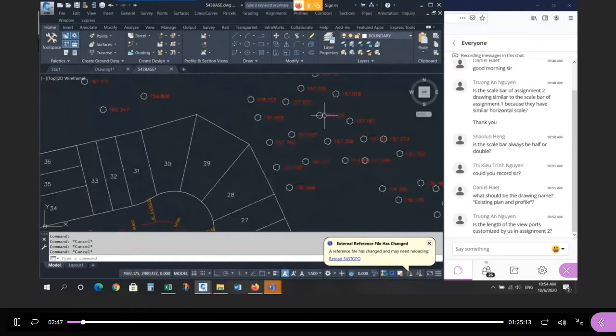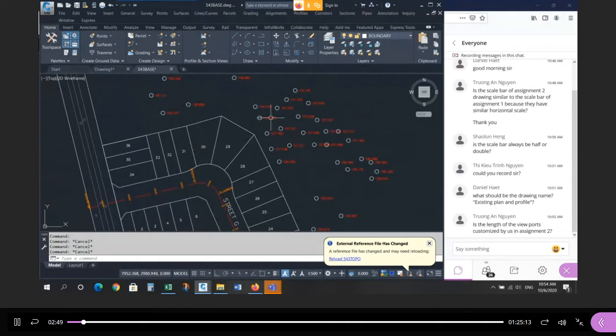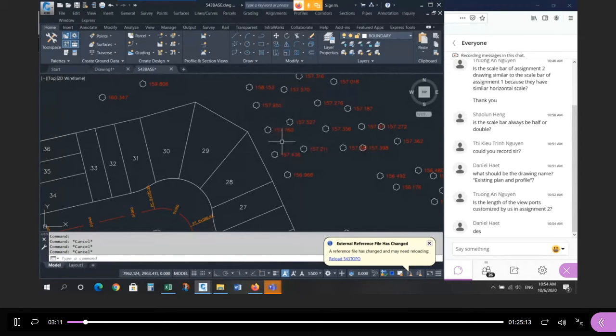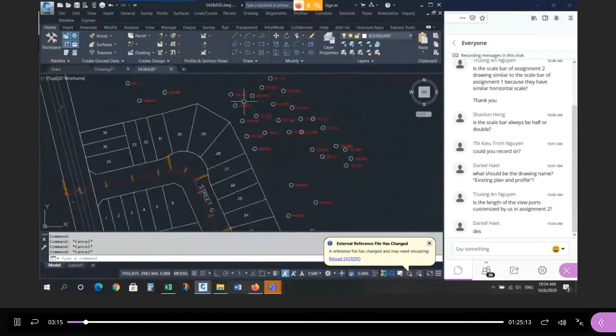Okay, now when it comes to the trees, if anybody wants to, I'm not going to be too picky, but we can change this. When it comes to the trees, what was the, do you remember the tree should have a label that shows what? What does your tree label show? Remember the tree, there's the number, the elevation, and the description. What does the tree label look like? Yeah, it's the description. So you want to be able to see, this is the only point layer. This is the only point layer that should be visible.